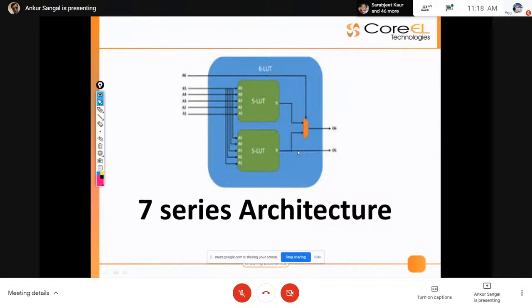So with only a single LUT, you can implement two Boolean expressions, and here the number of input pins is larger. That's why, compared to the older architecture, you can implement bigger Boolean expressions in this new architecture.